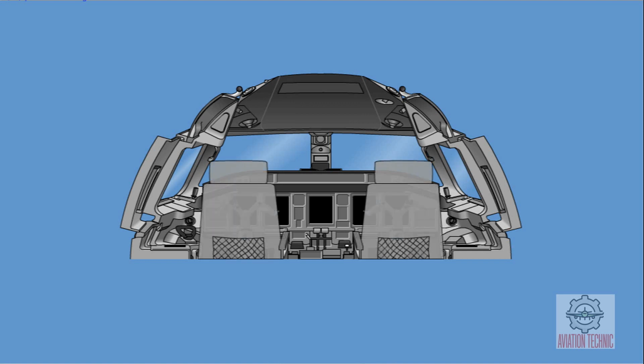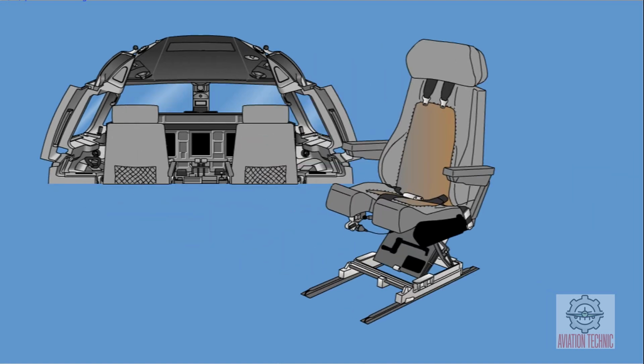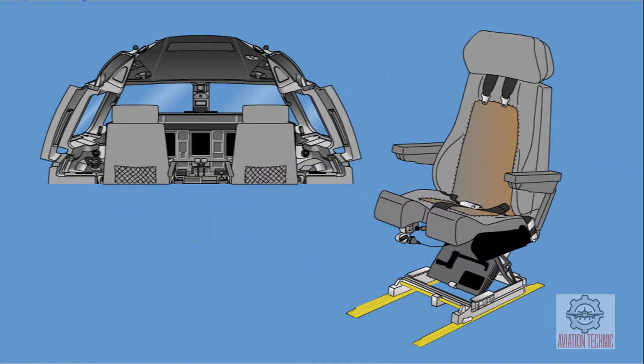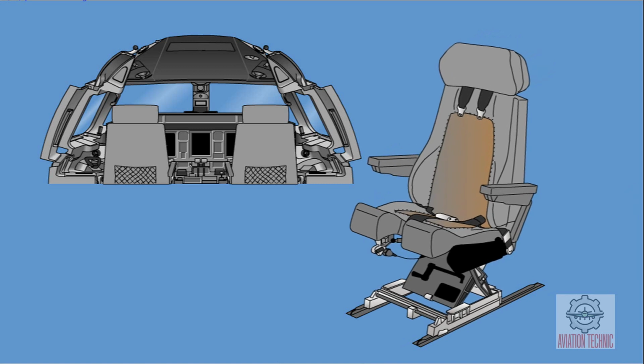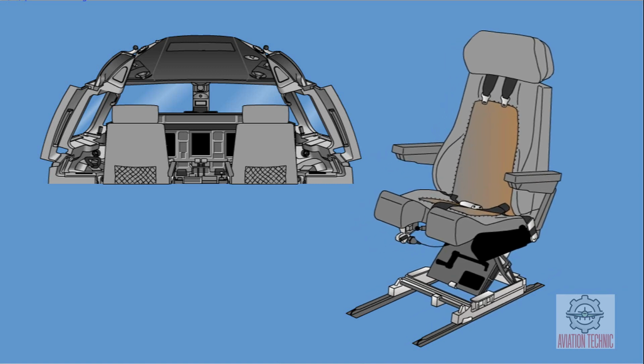The pilot seats are part of the Embraer 170 cockpit equipment. The seats provide accommodation to pilot and co-pilot during normal and emergency operations without increasing workload. Each seat is attached on 2 seat tracks which allow them to be adjusted fore and aft. A lateral outboard displacement allows each seat to be stowed while it is located at the rear seat track stop level. This position allows easy entry of the pilot or co-pilot without stepping over the central pedestal.